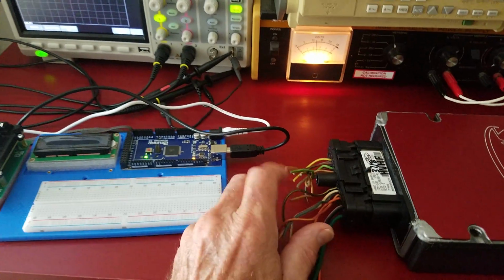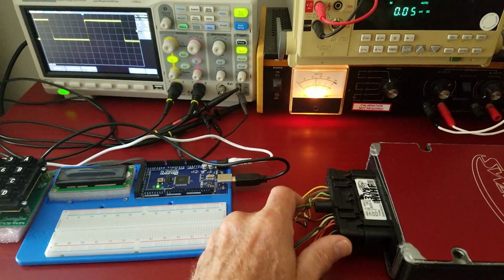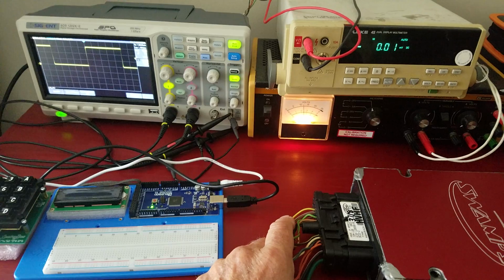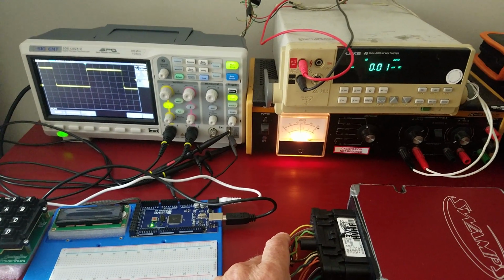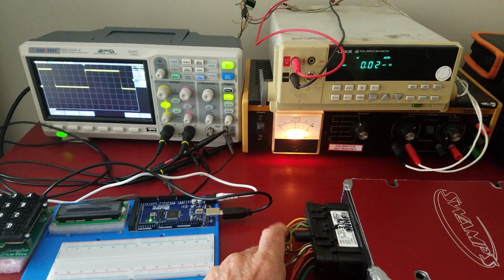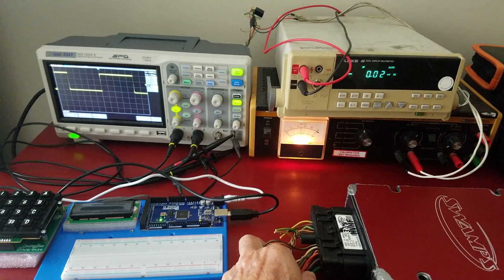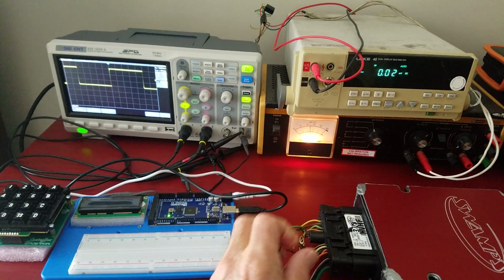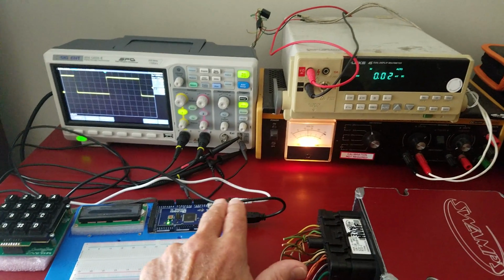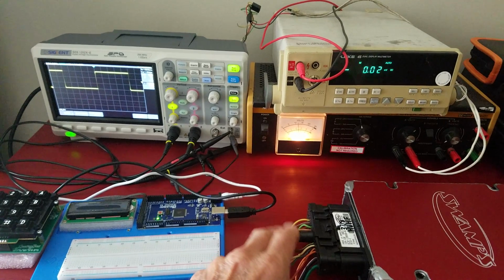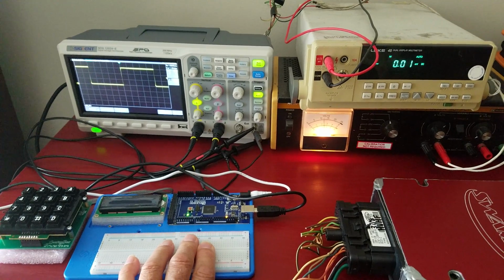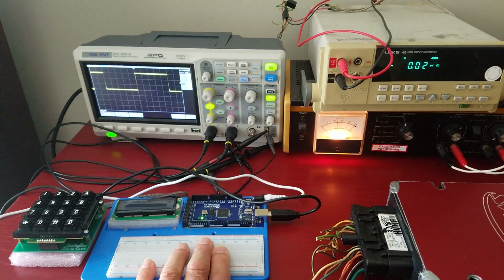Now, here we have a variety of inputs and outputs. There are inputs that indicate which series of injectors to fire based on the timing. This is designed for an 8-cylinder V8 Ford diesel engine, and you have all of the outputs and the ground for each injector. You drive four sets of injectors separately, and the processor will be providing the input control signals to do that. In addition, it will be monitoring the RPMs of the rotary expander.